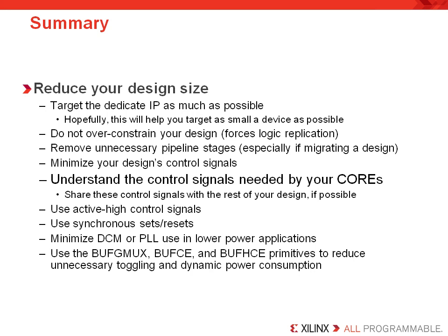Minimize the use of DLLs, DCMs, or PLLs in low power applications. And use the BUFG mux, BUFG clock enable, and BUFH clock enable primitives to reduce the unnecessary toggling and dynamic power consumption of your design.